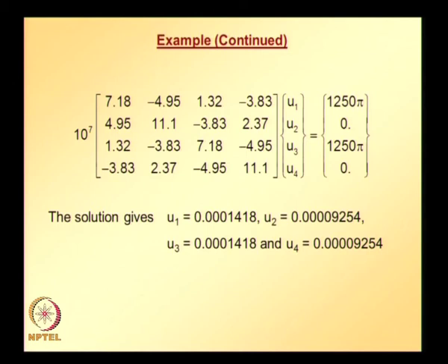And here calculations corresponding to one integration point will be shown. If you need to calculate stresses and strains at any point other than an integration point, we need to know the corresponding values of S and T at that point corresponding to the R and Z coordinates. Once we know the S and T values for the point of interest, you can easily calculate strains and stresses at that point once we find the strain displacement matrix.